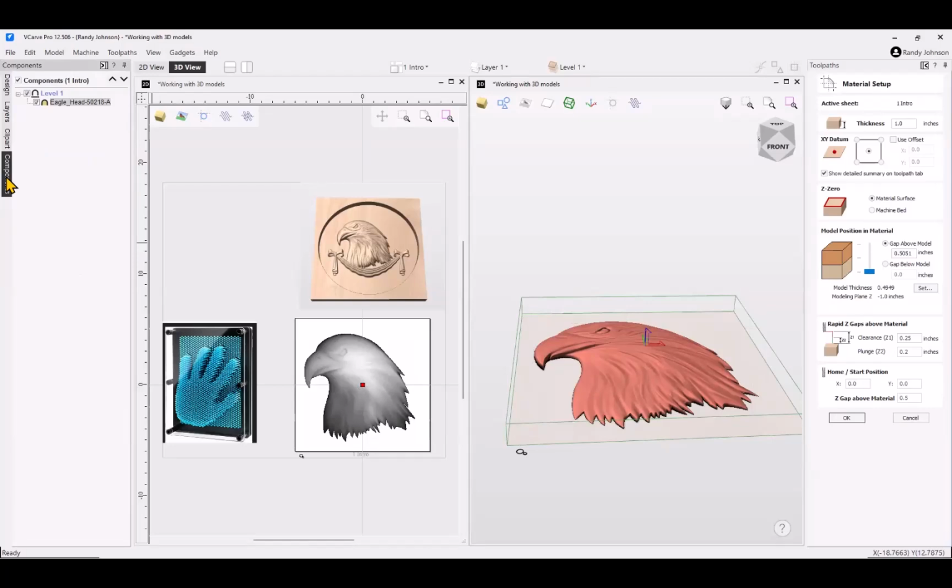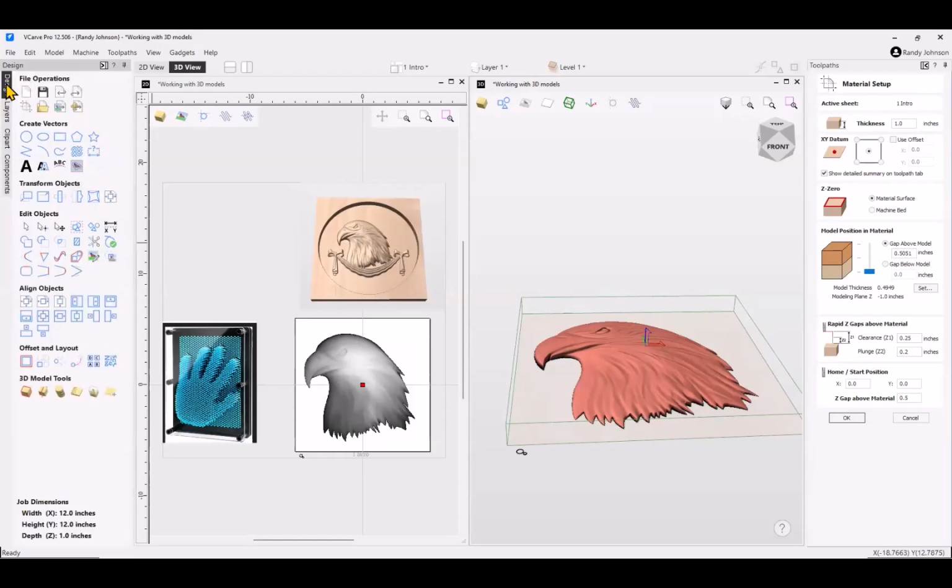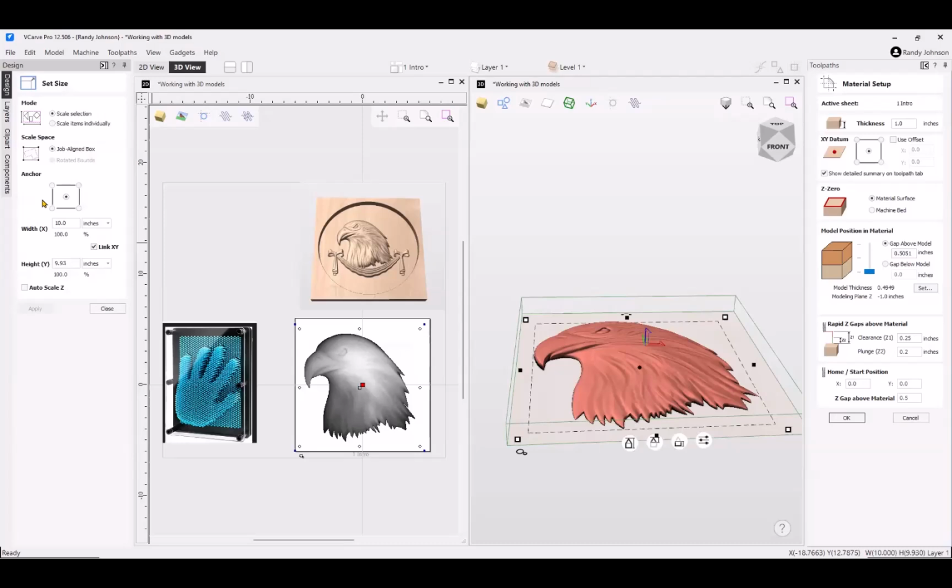Now, be aware as you're clicking around between these different windows, if I open up this window here, and I've got that edit window open, and then I go into my design window and try to do something, it may or may not let me do it. There are times when, if you have too many windows open, your drawing will lock up and you have to go back and figure out which window is open and close it out so that you can continue.